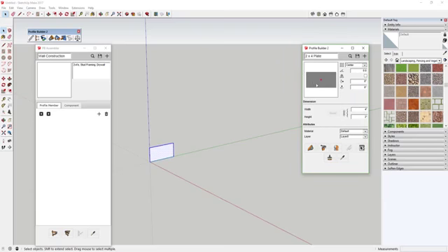You can see what that does is it brings in the shape that you drew as your profile. I'm going to set this so that when you bring this in, this little red dot is where your mouse is going to be when you click. For this profile, I'm going to do bottom right. Basically that means whenever you click, this is going to be your starting point and your ending point for your object. So when I click like this, you can see how this corner and this corner are where it's adding my object. So I've set my 2x4 plate as a profile in here.